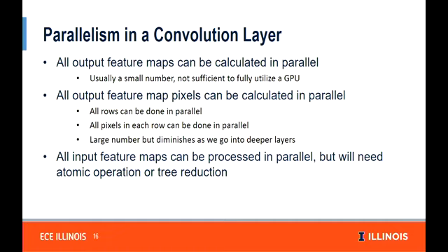But for this class, we're going to take it easy on you and let you use the constant memory for the weights. Okay, and for all the test cases that we're going to give you, they will fit into the constant memory. So this gives you a very big advantage in terms of bandwidth, because the constant memory is so well cached on chip that you practically only need to worry about the memory bandwidth for the input elements. Okay, so this makes the problem a lot easier.